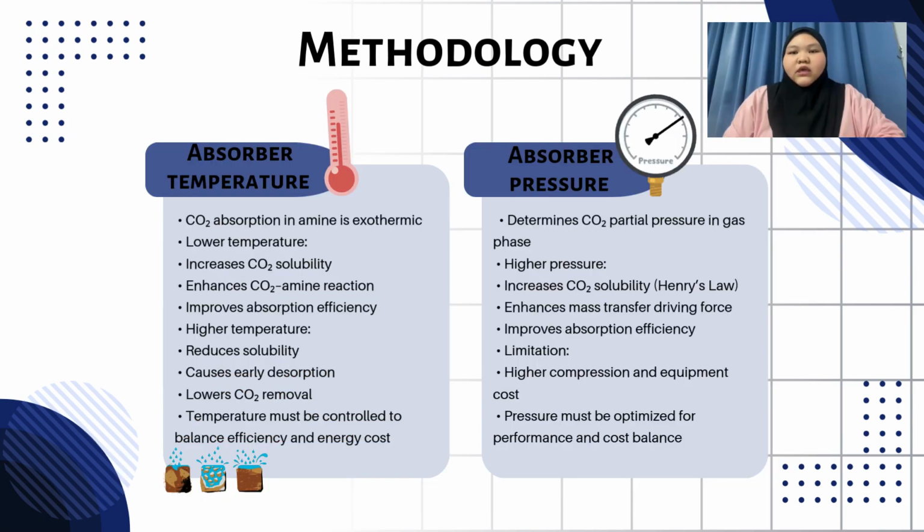Absorber temperature is very important in CO2 capture because it affects how easily CO2 can dissolve and react with the amine solvent. The absorption of CO2 in amine solution is an exothermic reaction, which means heat is released during the process. Because of this, lower temperatures are more favorable for CO2 absorption as they help form stable CO2-amine compounds. At lower absorber temperature, CO2 solubility in the liquid phase increases, allowing more CO2 to be absorbed.